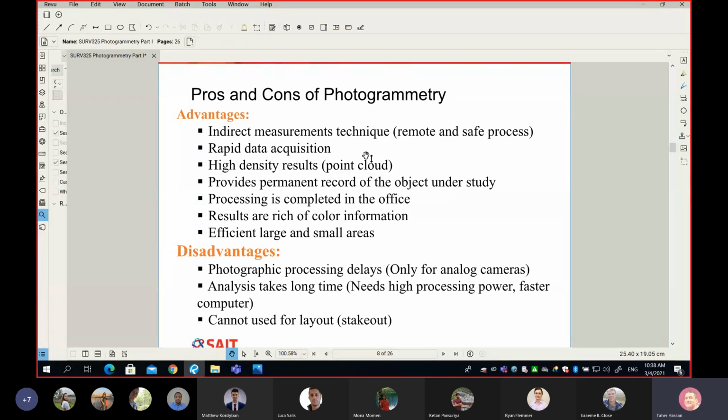And then here we go. Number two, we have some structures, for example, some old building that's maybe 1,000 years old, and those structures are about to fail. What is the best technique to do the 3D model? Photogrammetry or laser scanner. We don't have to touch the object because it's unsafe. And there are some areas which have hazards. Sometimes we have a tsunami, and sometimes we have an oil spill. What is the best way to create a map while it's unsafe to be on the ground? Simply photogrammetry. So that's why photogrammetry, being remote, is also a safe technique.